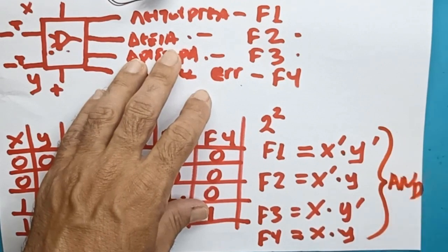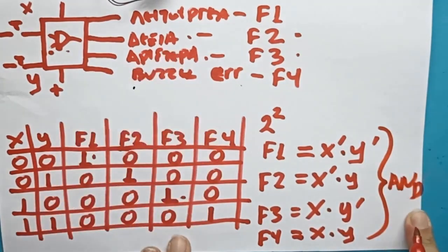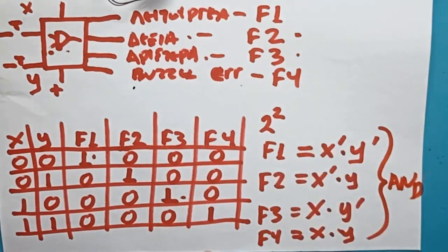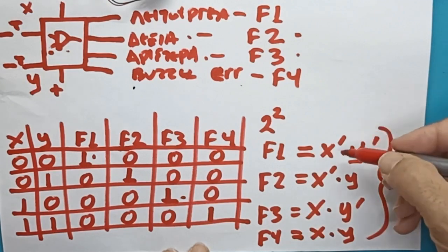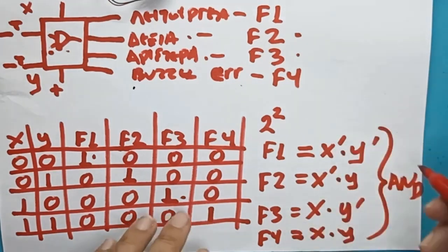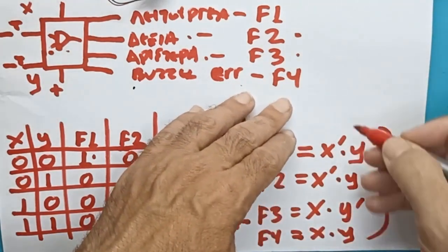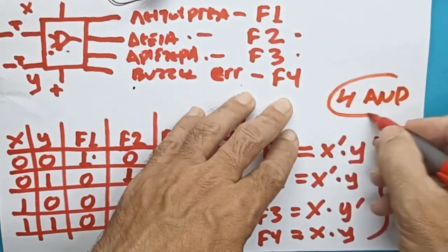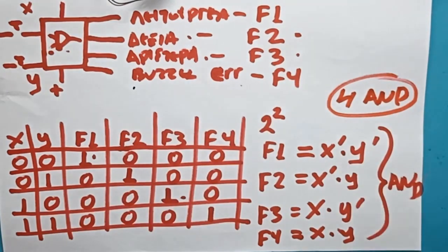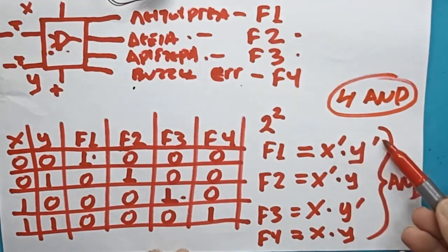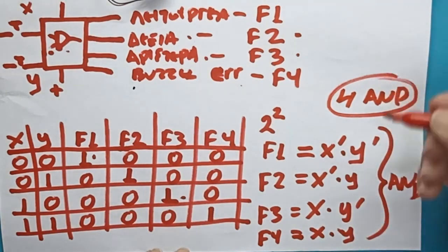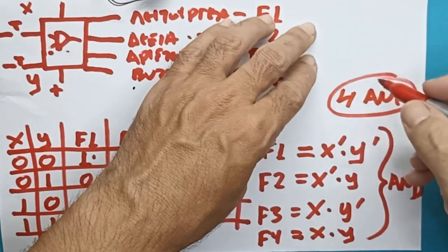And what do we see here now? That all these gates here are AND gates. Because they have the NOT in the middle, we see some variables that are complemented. So we also have NOT gates. We have 4 AND gates, because there are 4 product terms, so we definitely have 4 ANDs. And from the complemented variables, because our variables are 2, we need 2 NOT gates.